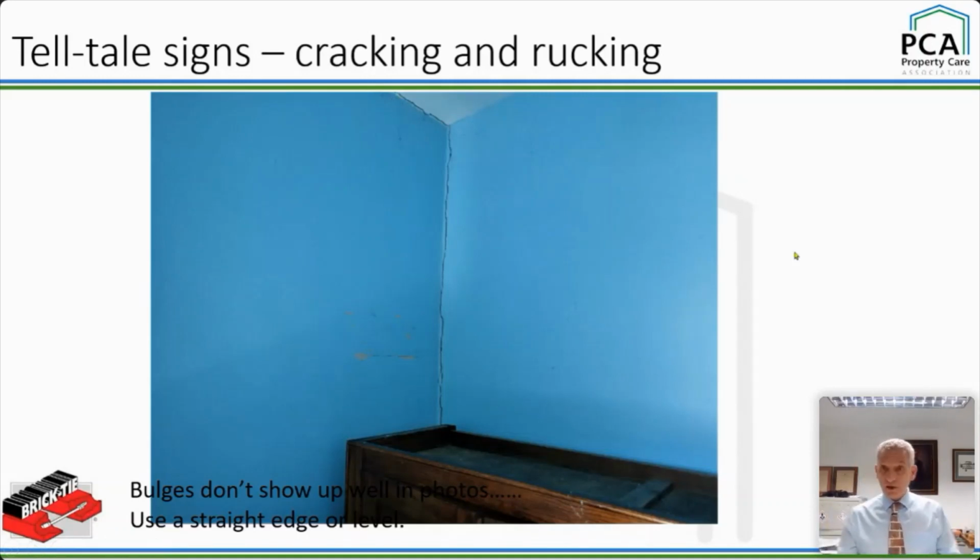There are other reasons for that crack, but one reason is the outer leaf may be moving outward. And just to touch on this, when the wind is blowing, you will have an alternating load, negative, positive, on the wall. And the wall is being shaken very, very gently. And sometimes if we've not got a good firm connection, it doesn't have to be anything massive, but if we've not got a nice connection to the superstructure, the inner leaf may move out microns or a millimetre.